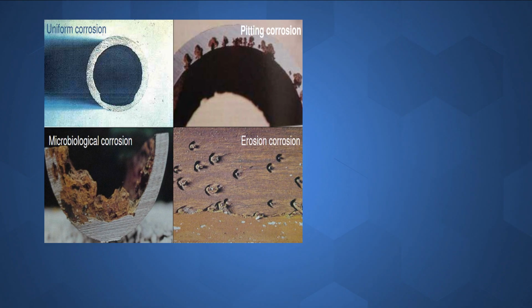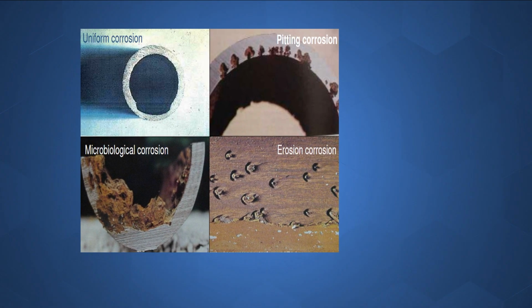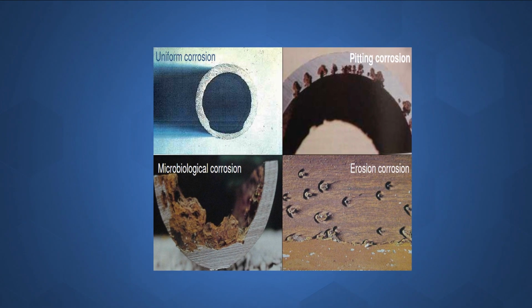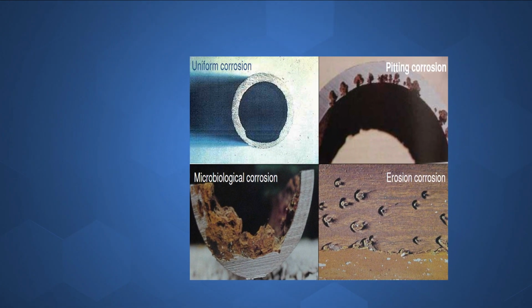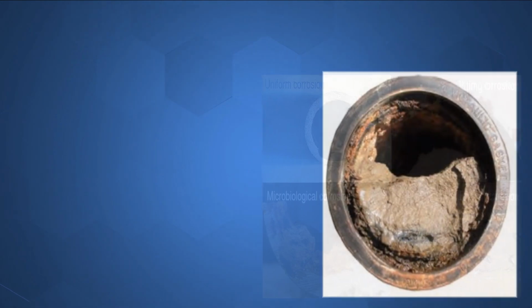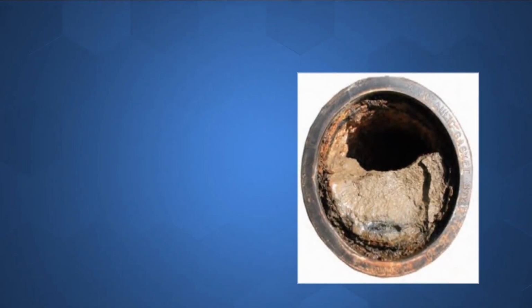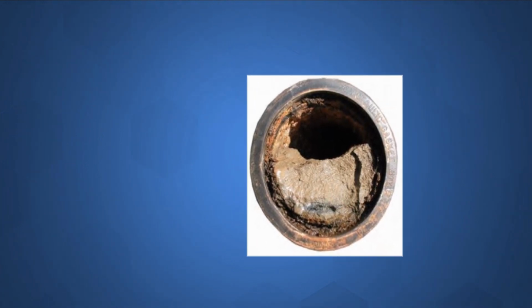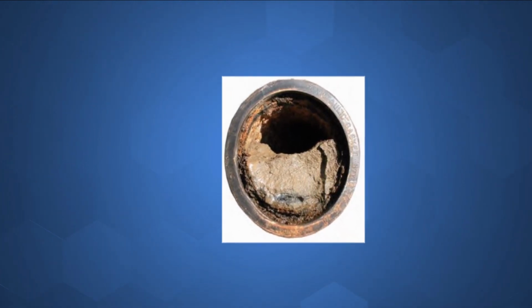Corrosion in a heating or cooling system can cause a number of issues, including wear and tear, and leaky pipes. Leaky pipes lead to higher use of water and chemical, and a loss of metal within the system leads to equipment failure and costly repairs. Corrosion byproducts such as iron, dirt, sludge, and debris also contribute to deposit formation. They can plug up pipes and pumps and cause leaky pump seals and valves to fail.